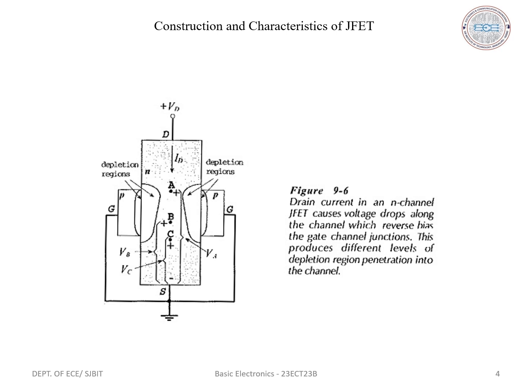The ends of the channel are the drain and the source. The two P-type materials are connected together and form the gate. When the gate is not connected to a supply voltage and voltage is applied across the drain source terminals, a drain current ID flows as shown in the figure. When gate source voltage is applied, with the gate negative with respect to the source as shown in the figure,